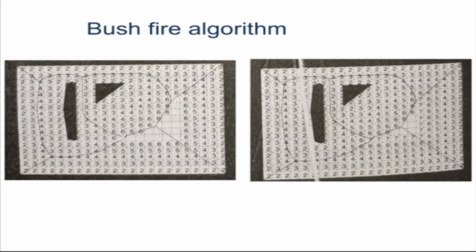Now there are other methods, fast methods by which you can make this deformation retract. Bushfire algorithm is one of them, where the object is marked as 1. Okay, the figure, the number 1, and then the adjoining cells. So this is basically a grid, kind of a grid workspace. And a computer can compute this very, very quickly. So this is given 1, 1, 1, 1, and the next grid to 1 is given 2, then 3 in that order. So you can see this is 2, then 3, 4 in that order. Similarly, from the boundary of the workspace, we start with 1, this becomes 2, then 3. Now you can see that it can go maximum till 4, and then it starts meeting.